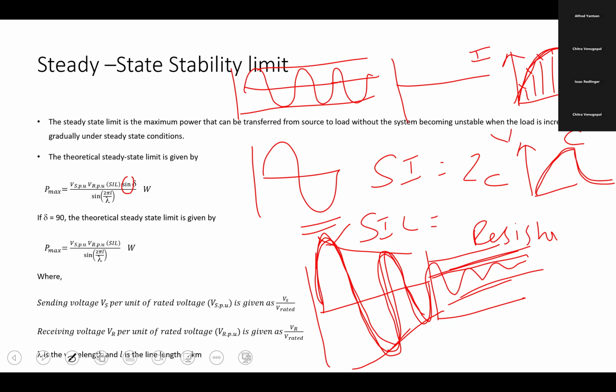I was kind of thinking, essentially when the motor starts up, we know how much time it'll take to get to the equilibrium. Stable. Yeah. But with a fault, if it exceeds the amount of time, we then know it's a fault. Right. I will look at the peak of the current, the maximum value. Yeah, that's another point. Sometimes if the value is too much, yes, correct. Both are good points.